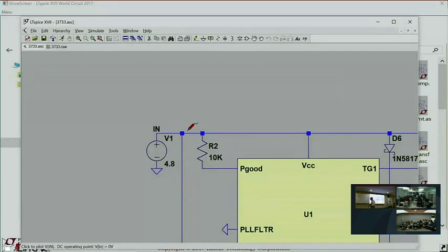Otherwise, the ripple in the inductor will travel all the way down to the harness wiring or PC board traces to that thing, and you don't want that RF going down there. You want DC in and DC out. You don't want DC in and RF out the input and just DC out the output. You have to filter. You have to bypass the input.